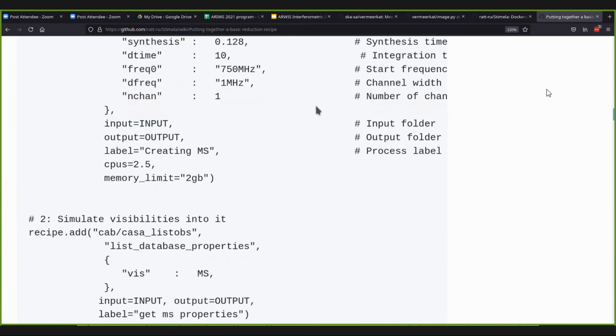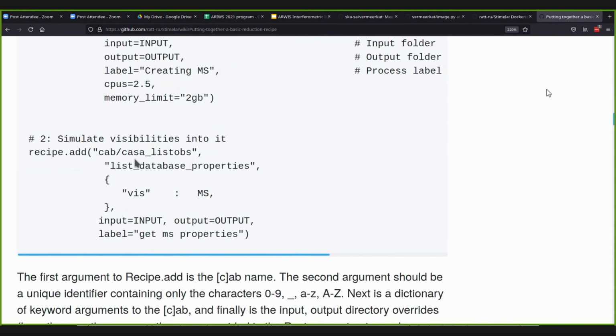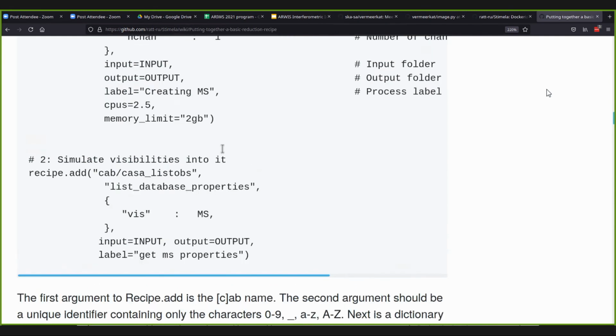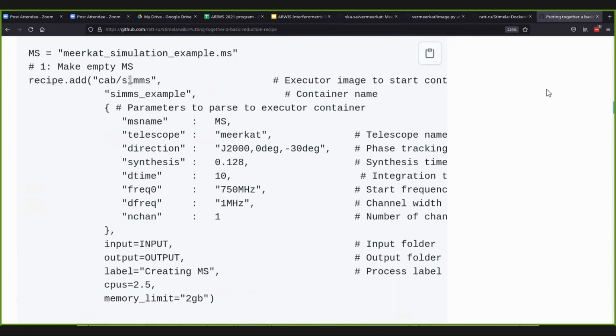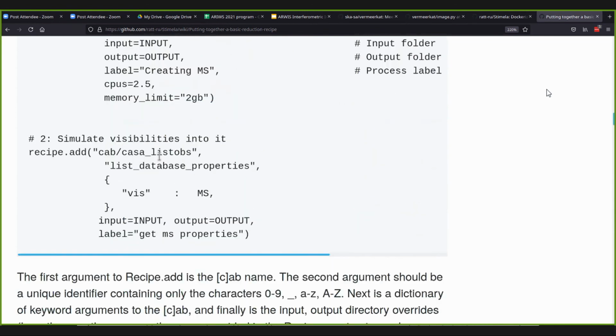It will put the measurement set into what is called the MSDir. So there will be an input directory, an MSDir directory, and an output directory. We put it into the MSDir directory and write out any other outputs into the output directory. And that's in your current working path. And then we call this wrapper function, which is outside of CASA, the SimMS wrapper. And then, for instance, we can even execute basic CASA operations using this.